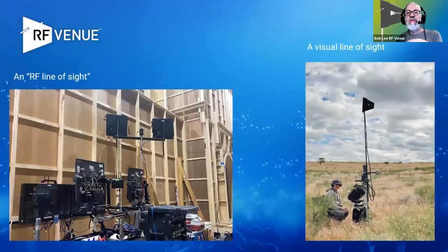In that space, the RF energy may encounter surfaces or materials that reflect radio waves, or maybe absorb them, or just pass them through. In general, it's good practice not to have any obstacles that absorb or reflect RF between the transmitter and the receiving antennas. Now, you need a clear line of sight. A visual line of sight, that you can see with your own eyes, is always good.